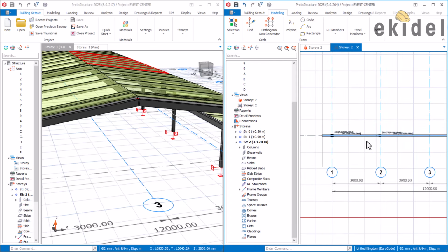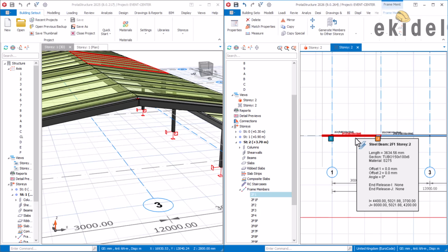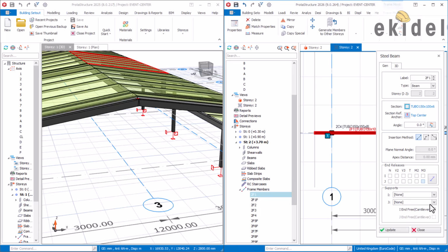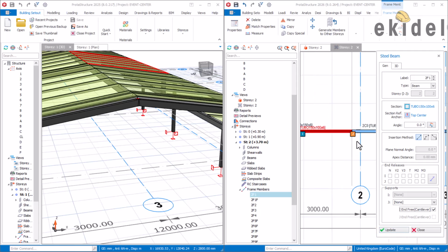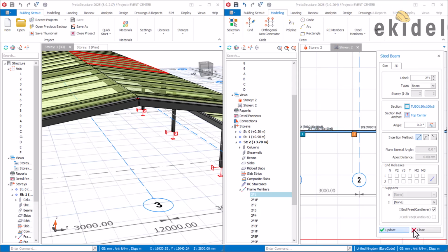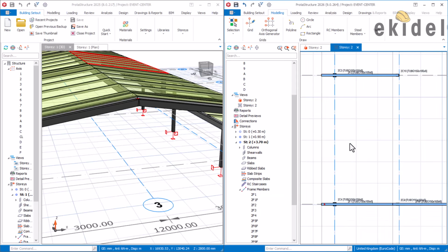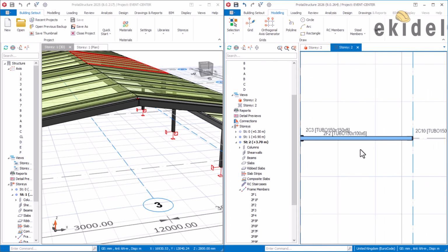So what I'll do now, I'll come now, click on this here. Since both ends are free, I'll click on this and make sure I turn this on. Okay, cantilever here, and I'll click on what? At this end here, at the I, because I is free, but J is not free. So I'll come and do what? Turn this on here, and I'll say okay, that is fine. So we'll have that now as a cantilever here, and again do the same thing for these other ones here.